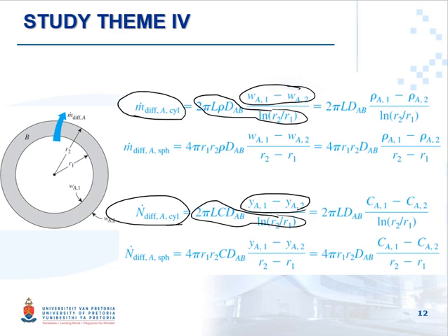For spherical coordinates, or one-dimensional non-reacting mass transfer, again steady and one-dimensional but in different coordinates, when we are speaking about the mass base, what is important for us is m dot, driving force mass fractions divided by resisting force.